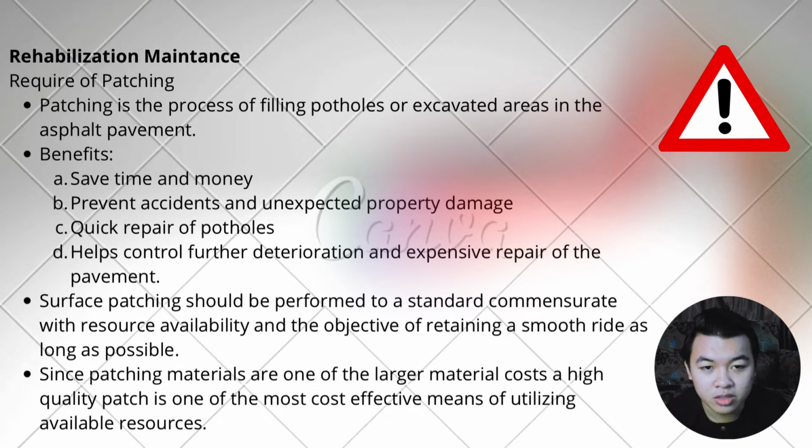Patching is the process of filling a pothole or excavated area in the asphalt pavement. Among the benefits of the patching method is that it can save time and save costs for road repair work. Furthermore, this method is also suitable for repairing potholes quickly and can help control further deterioration and expensive repair of the pavement.